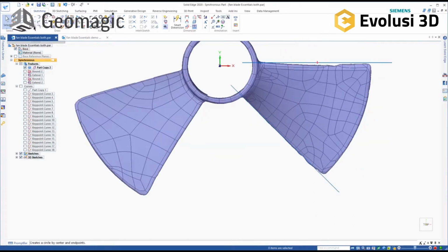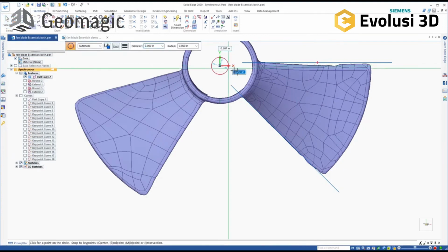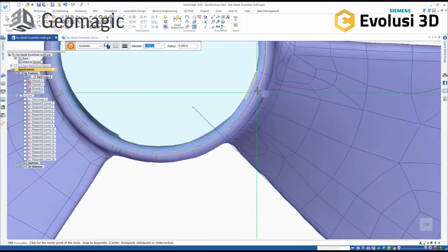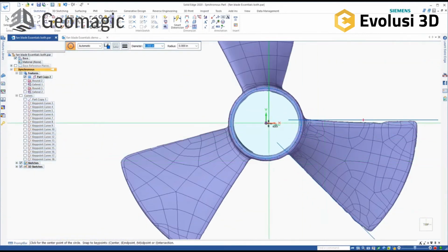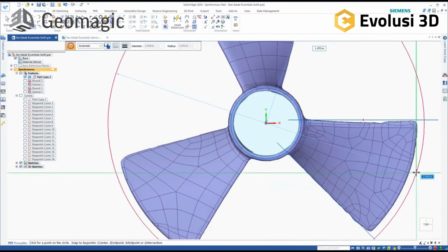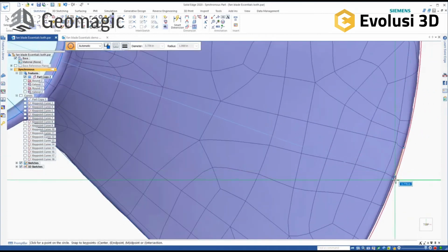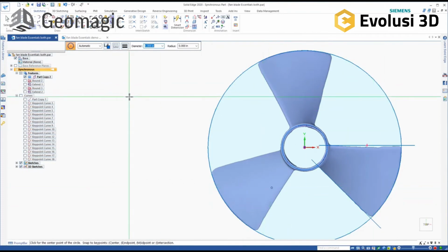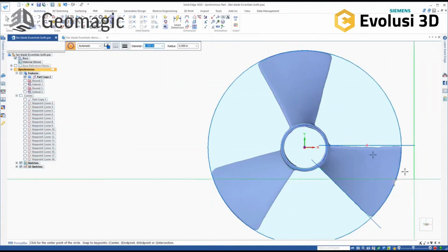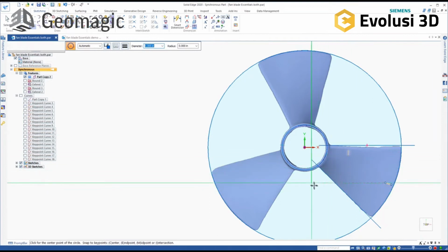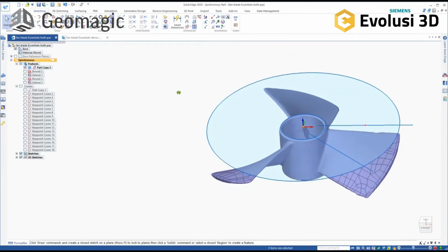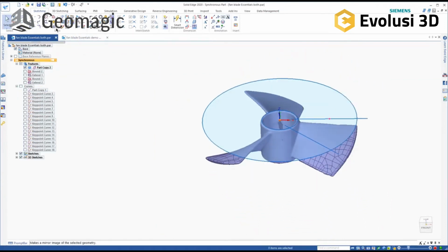And then I'll go ahead and draw a circle from the middle, and I'm going to just draw it down the middle of this solid there. And you'll see here in a second why I'm doing that. And then we'll snap that to the outside. So with Solid Edge, I don't have to necessarily trim all these pieces together. I can just rough out my sketch and then get out of it and then come over and do an extrusion